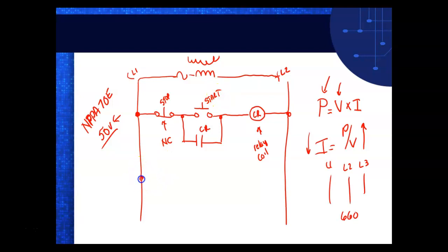Then I come down here and I might do what? I might put another circuit. So these circuits that are drawn between L1 and L2, these are referred to as rungs. And you can see why it's given the name a ladder diagram, because it basically looks kind of like a what? Like a ladder. So we have two power rails. They're vertical. They're always vertical. And then we draw our individual circuits between L1 and L2, or between CL1 and CL2, whatever it's called at your plant that you go to work with. And each one of these are called a rung.